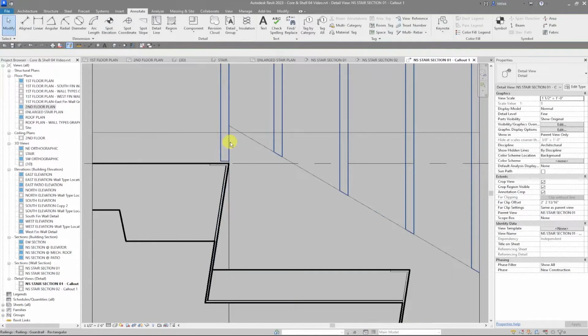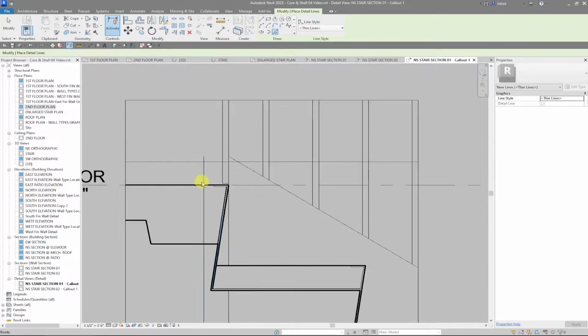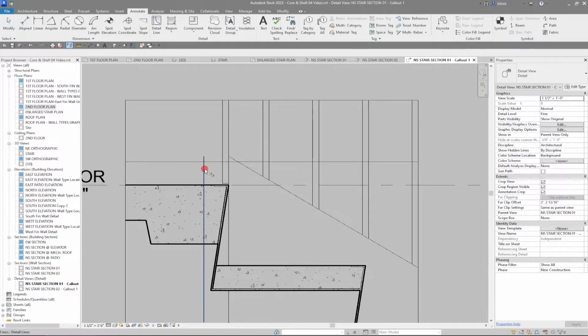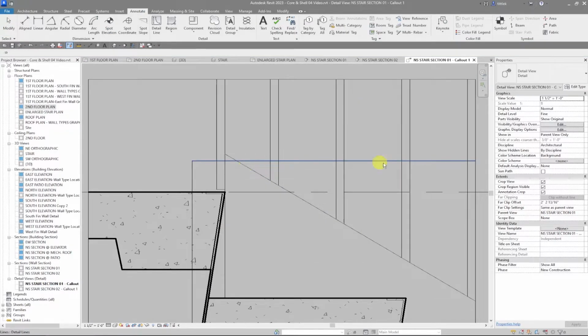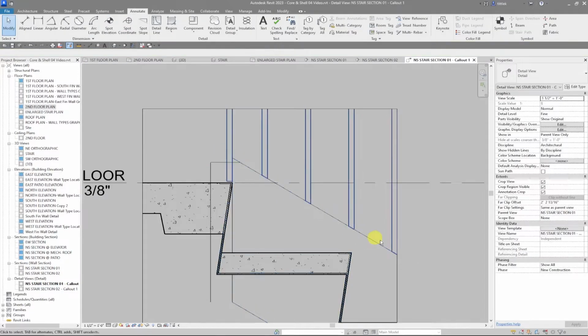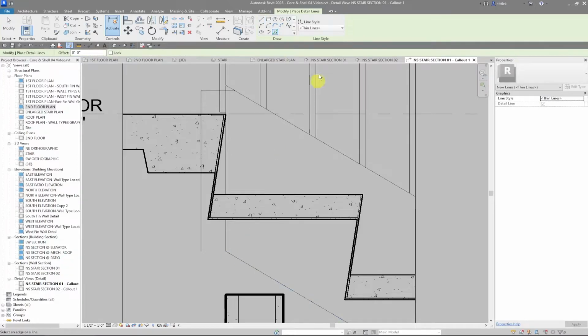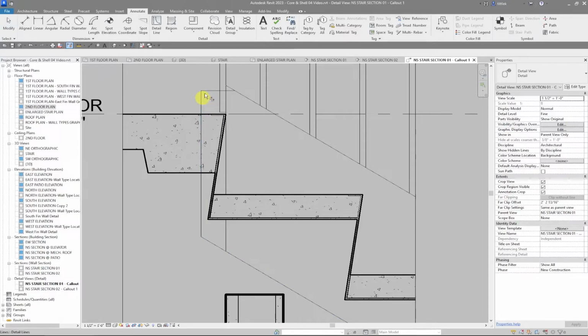There's that 2-inch line. Now I can also draw with the 2-inch offset the vertical line, because this vertical line is still here. So I can pick lines, 2-inch offset, pick this line. So there's the extent of that. I can trim that to that, and this one I can't trim, but I can, where is it? Is it all the way over here? Yeah. I can pull this back until it touches the stringer there, and then again, detail line, pick lines. I'm going to pick this line here, and now I can trim this line to there. I've already trimmed those together.